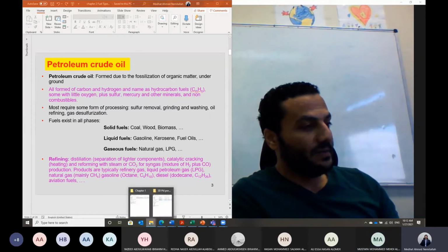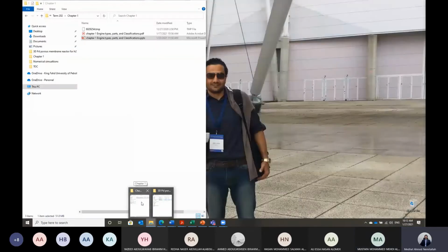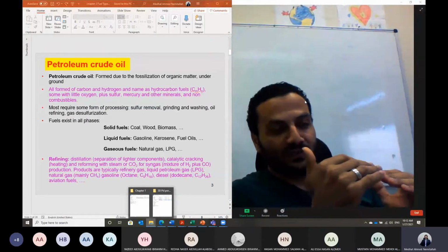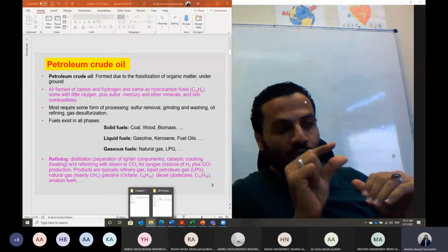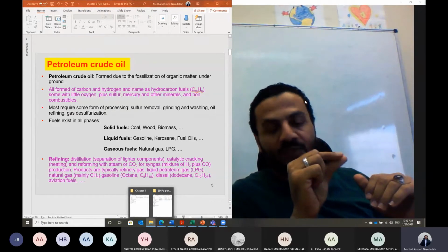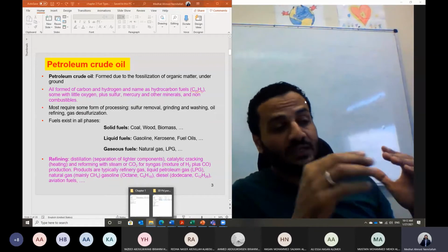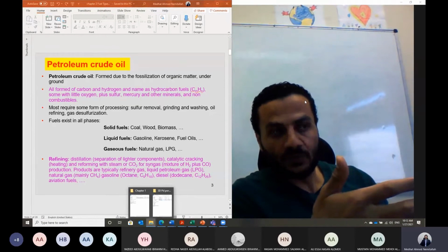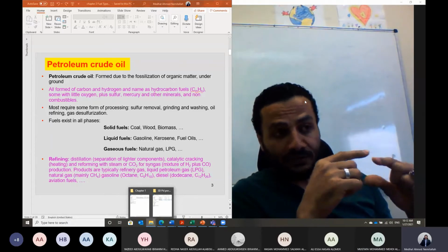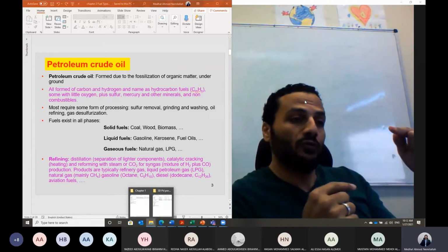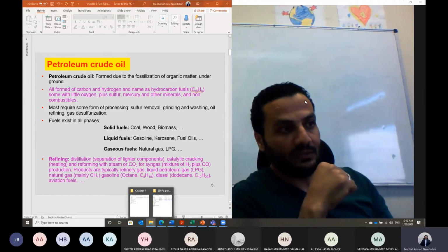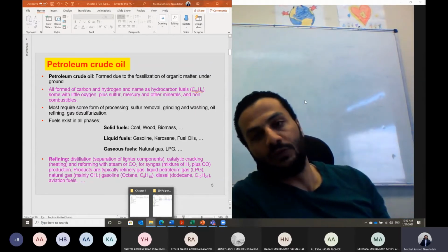Valve lead. At low engine speed, we need the intake valve to open for a short time and a short distance, a short lift of the valve. And at high speed, we need more air plus fuel. So in this case, we need the intake valve to open for longer time, and it should have a longer depth inside the cylinder to allow more air plus fuel to get inside, because at high speed we need high power.